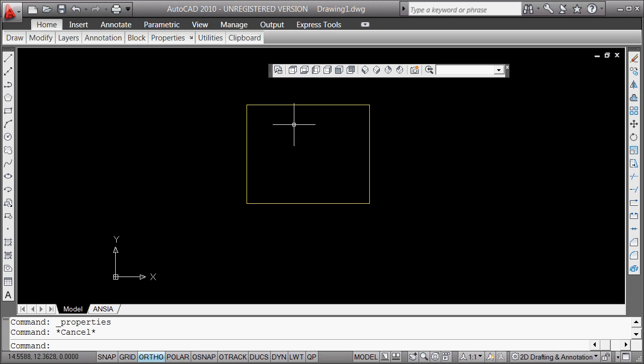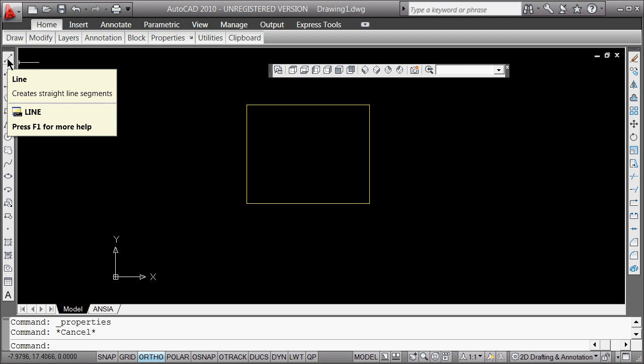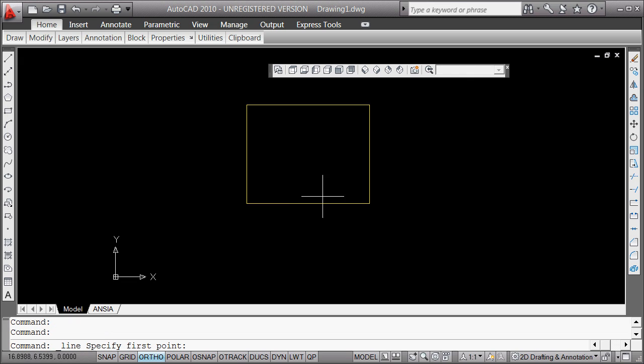Alright, so what I'm going to do first is arbitrarily draft a line that's going to be the center line. I'm using the line command, just picking this using my eye. You know that piece is 5 tall, so I'm going to go here, and then say at, and I'm going to make it arbitrary, 10, angle 90. Okay, so now I've drafted in a piece here. I'm going to think of that line as going all the way from the bottom up through the top. So now I can start using offsets to my major kink points.